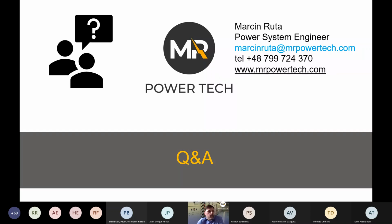Okay, so there are differences because now you can more precisely specify your electrode configurations. So if you followed VCB or HCB before, probably you will not see a big difference. But if you start now to see some VCBB, vertical conductor breaker barrier, so now you might see change.